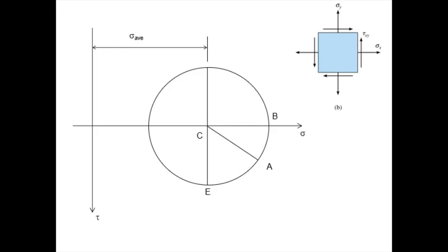So you tend to draw the shear stress axis towards the left of your graph paper if you use a graph paper. Otherwise, just sketch a line, vertical line on the left of your plain paper. And then you have your horizontal axis right in the middle. Okay? And that represents the normal stress. So that's sigma. Normally we have megapascal as the stress values. Okay? So we have tau. Also we have megapascal as the unit. And this is positive downwards or counterclockwise. Okay? And so up here is clockwise or negative.